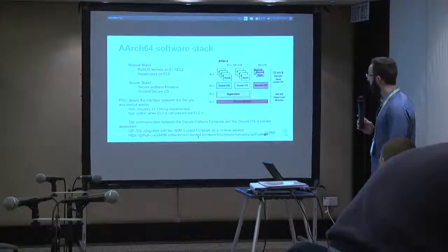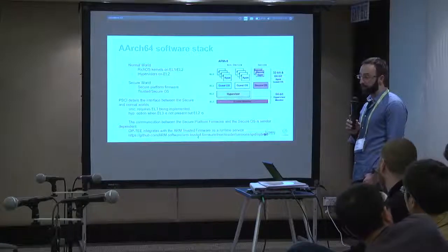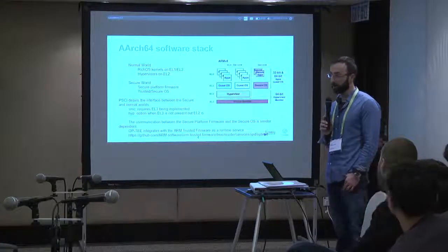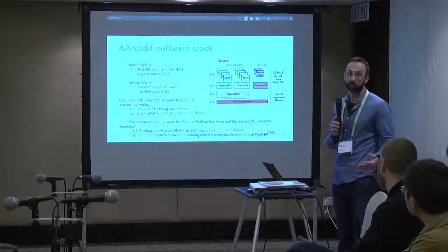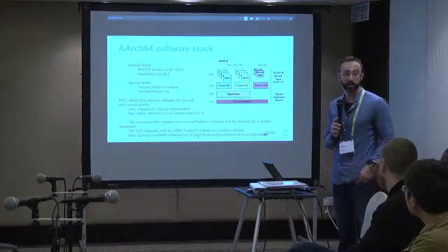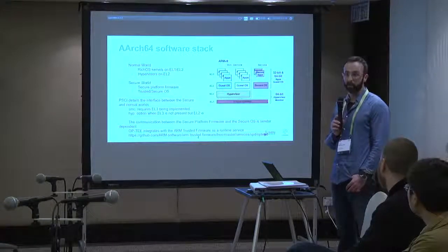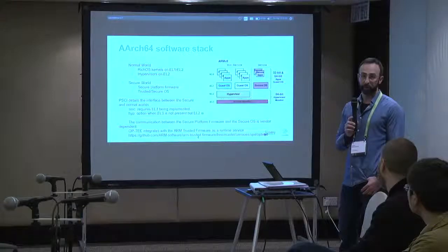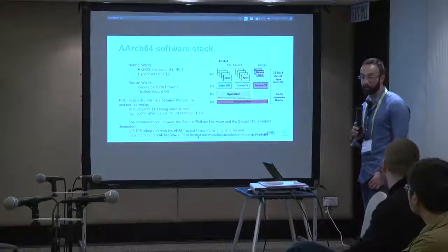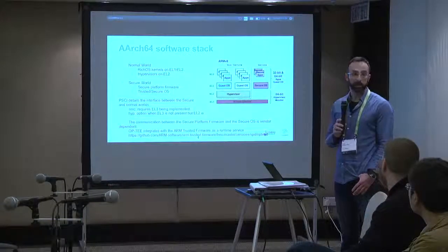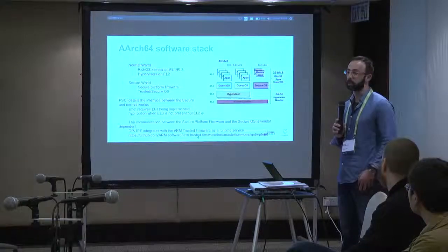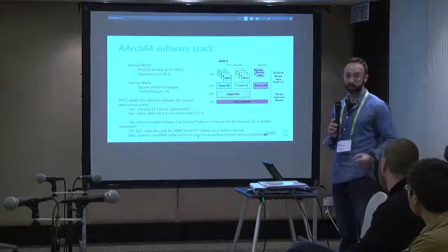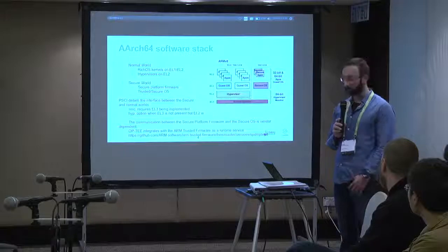The way OP-TEE works with the ARM Trusted Firmware: what has been done by the security team is they integrated OP-TEE with the ATF as a runtime service. So basically, when the system boots, OP-TEE registers its hooks with the ATF.